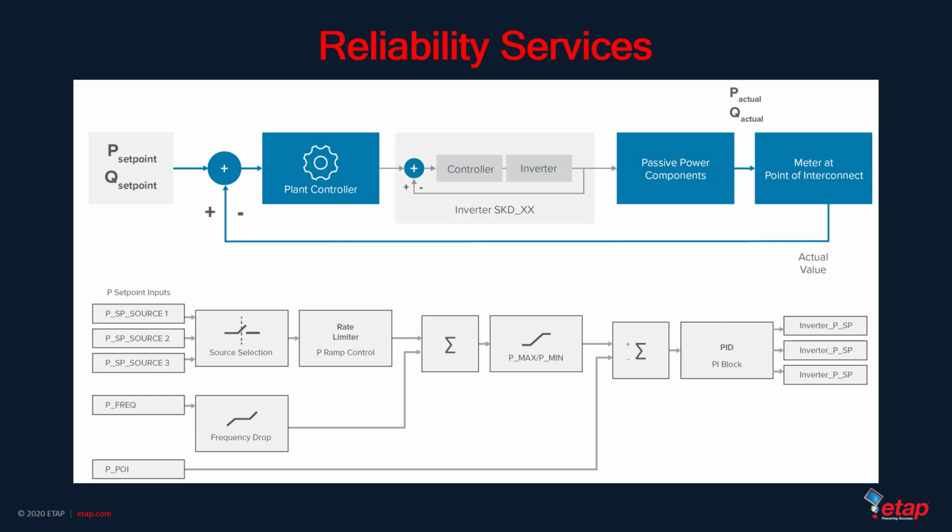Unlike traditional generators, the prime mover or fuel source is often uncontrollable. With PV generation, weather and sunlight conditions cannot be controlled. Irradiance may be too low or irregular for the plant to meet the demand. Similarly, partial cloud cover can affect different areas of the plant disproportionately, causing the output to fluctuate.